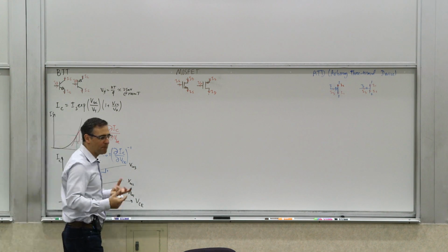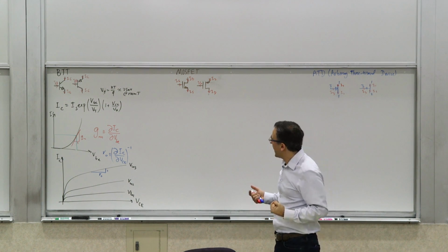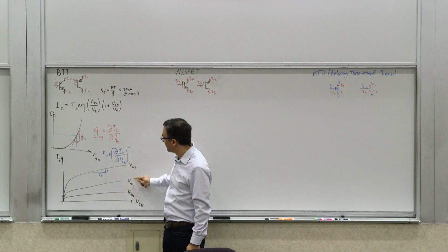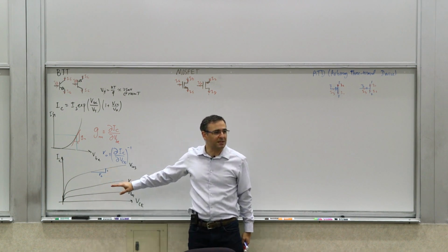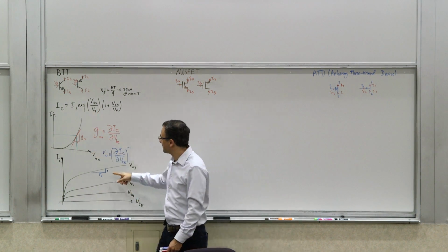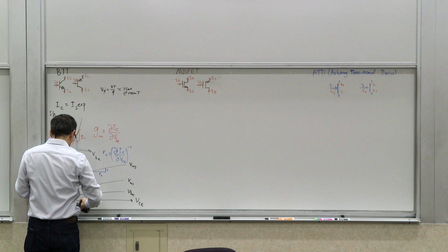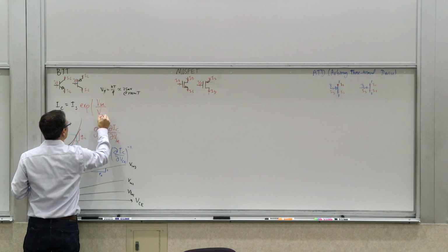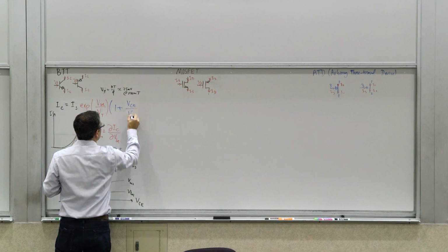So this is the basic property of the transistor, right? And it's also because of this exponential behavior, you can see that for equally spaced VBE, this spacing is increasing. So these are not equally spaced for equally spaced VBE because of this exponential behavior. So this is really capturing this part, and this is really capturing this part. I might as well just rewrite these with these colors. So you can say exponential of VBE over VT and 1 plus VCE over VA, which is the early voltage.